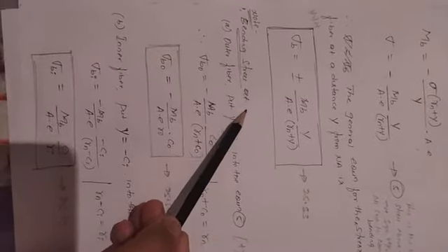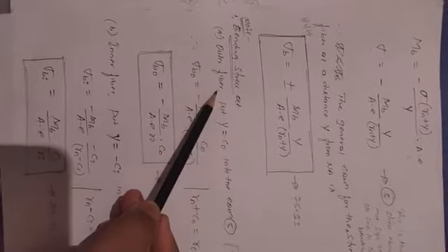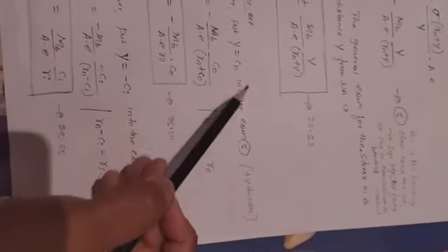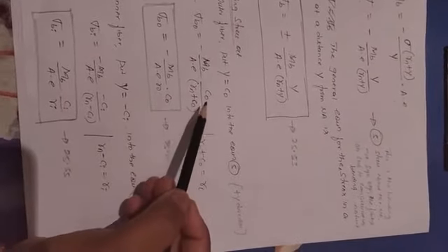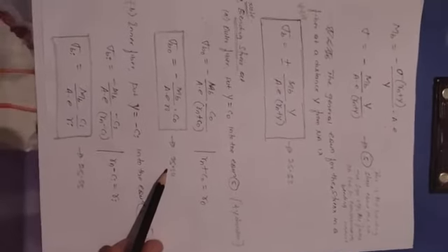Now the important one is the bending stress at the outer fiber. For the outer fiber, what is the y value? I can substitute y is equal to c naught. Above the neutral axis is the positive y direction, so plus c naught. For the outer fiber y is equal to c naught. Substitute into equation number 5. Now you will get this equation, then substitute plus c naught wherever y is there. Now we know that Rn plus c naught is equal to R naught. This is equation number 25.54.